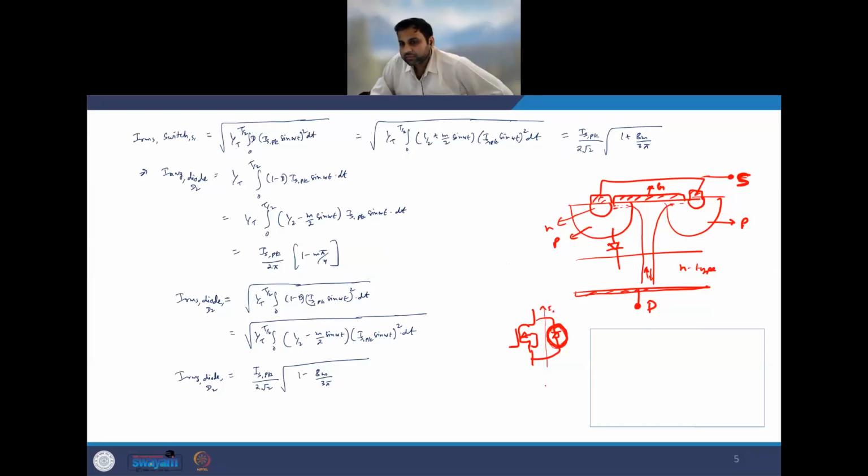And at the same time, when the current is going through the diode, if I create the channel, the current will flow through the channel, and RDS on times I naught, the I value which is going, is less than my V forward